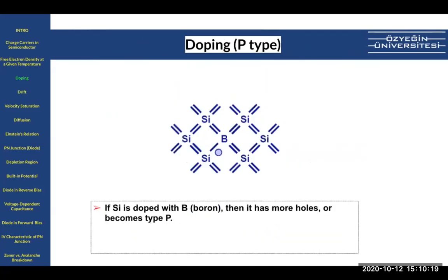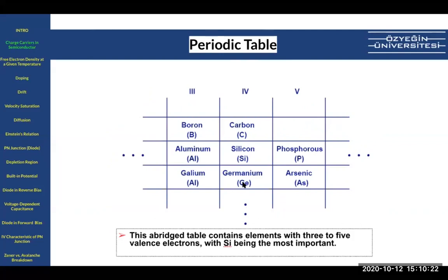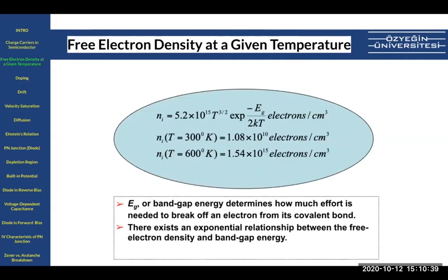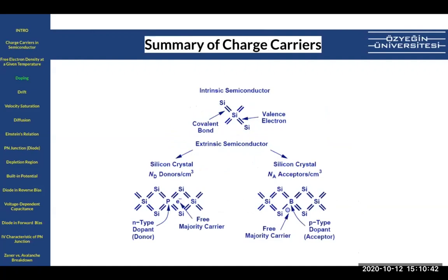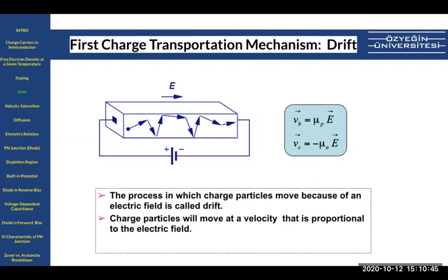Thank you. No problem. For instance, germanium is also used a lot in the military, but the military doesn't care about the price. So mostly germanium structures provide much better circuits and systems because their performance is much higher. That's why the military uses germanium, but in mobile electronics, like consumer design, like cell phones, TVs, game boxes, they usually design all these circuits with silicon because it's much cheaper.